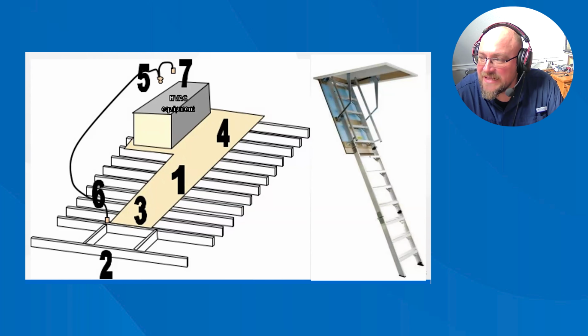Fastened with insufficient number of nails or screws. Manufacturers provide a certain number of nails with instructions that they all be used, and they probably do this for a good reason. Inspectors should be wary of place nail here notices that are nowhere near any nails, like we just discussed.